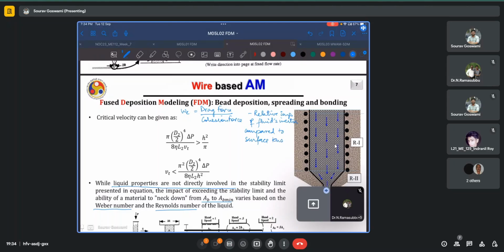So these factors will become especially relevant if you have, say, a multi-phase flow consisting of two fluids with different surface tensions. So Weber number is mostly encountered in such situations or modeling of such cases. I will also simply write that here, so it is useful in cases where there is an interface between two different fluids, especially in multi-phase flows.